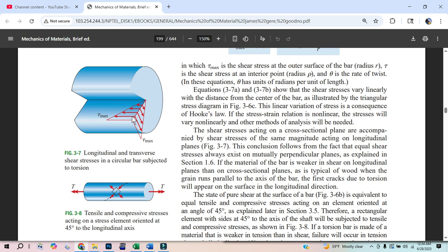That's going to be this arc length that we took, which was the angle of twist divided by 360 times the circumference. And then I'm going to divide it by this length of the cylinder, and that's going to give me this shear angle. That's what's happening at the molecular level. We're getting one molecule of disks to slide across another molecule of disks, making an angle. That angle is hella small. But like I said, if you have a meter long bar, that small angle adds up to like 4 millimeters. But anyway, so we've already worked in reverse and we know what that angle is.